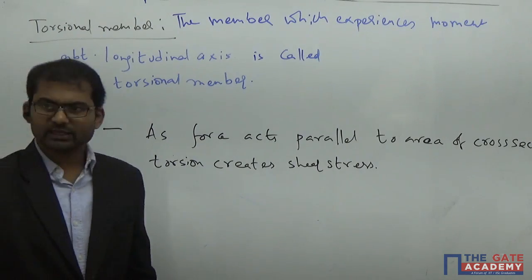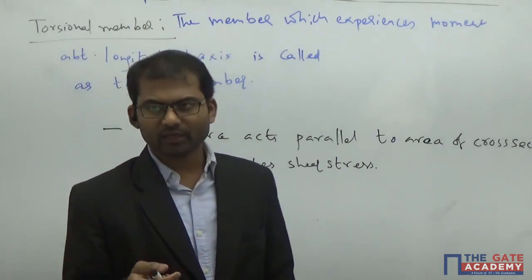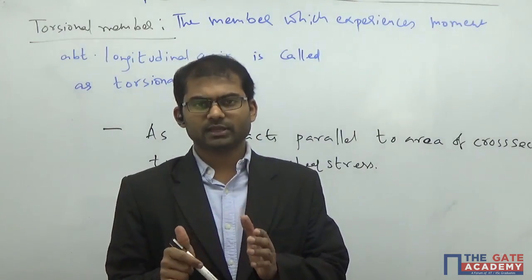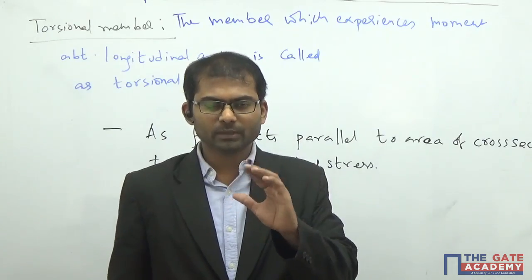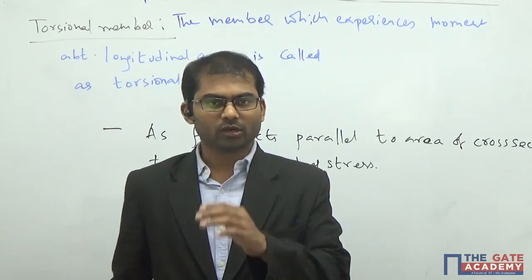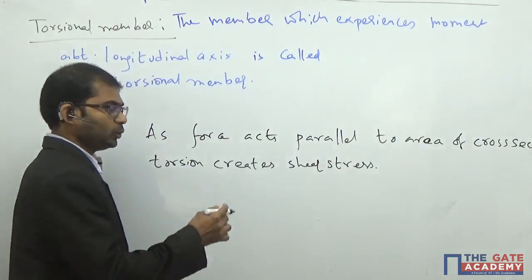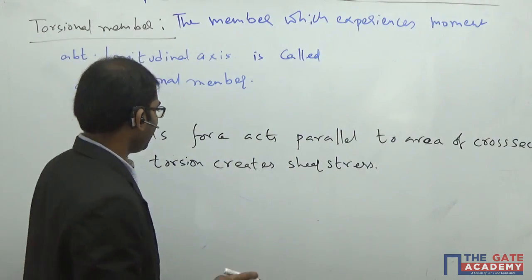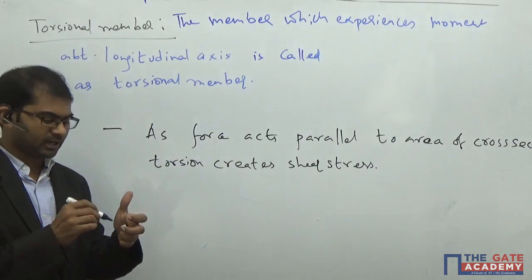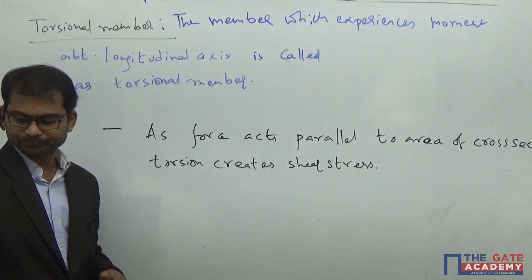See here, actually, there is a difference between torque and couple. Basically, generally we can take torque and moment to be the same here, but there is a difference between a couple and a torque, because a couple means two equal and opposite forces separated by a distance. Understand? Please copy this one. Once you're done with this, I will explain the difference between couple and torque here.